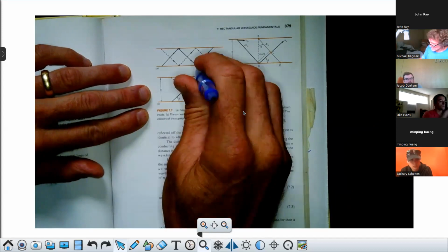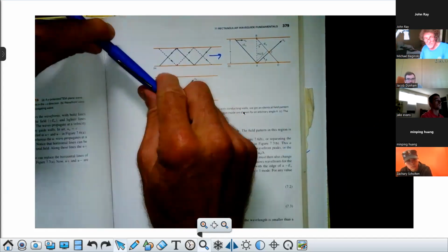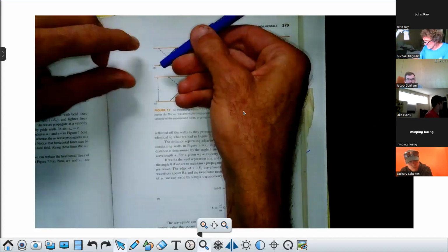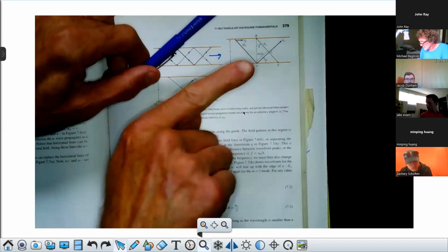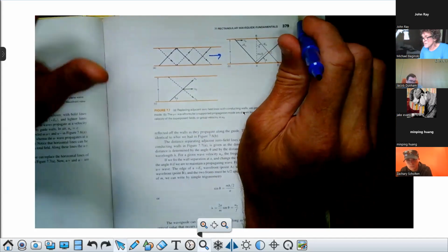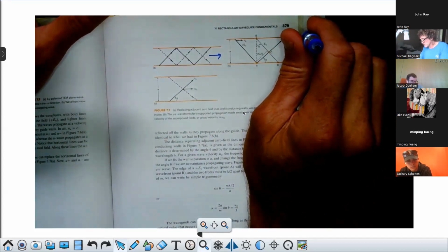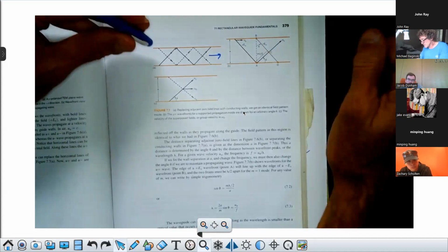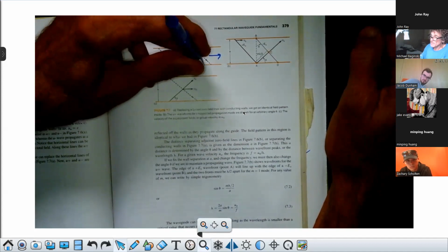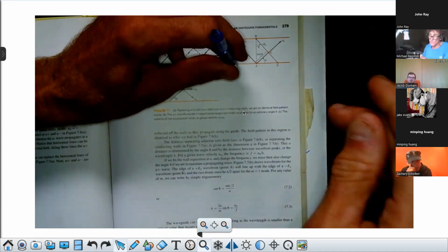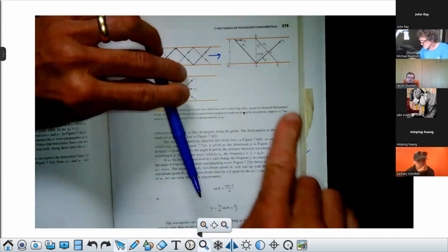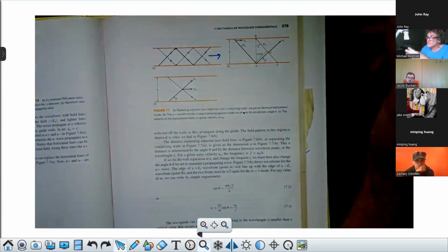All right, now the electric field could also be in this direction, and then you could see it would have a component of the electric field in the direction of propagation. So just like we did when we talked about oblique incidence, if we have a mode that is TE, where the electric field is transverse to the direction of propagation, we analyze it differently than if we have a magnetic field that is transverse. The electric field would now have a component in the direction of propagation. Can you appreciate that simple fact?